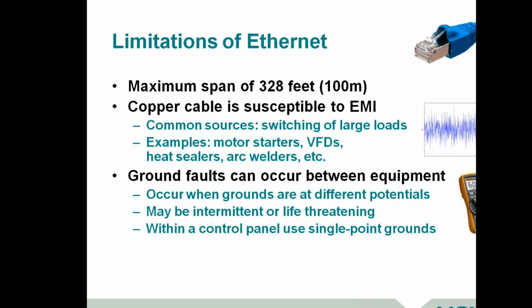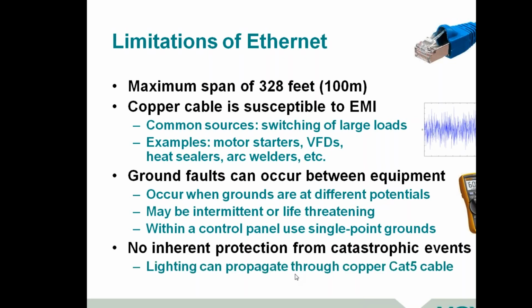Some of you who have been around a while have found that you need to be careful when plugging in test equipment or even a laptop. I know in a past life as an applications engineer, a common thing was if you weren't careful, you'd take out the ports on your laptop, and that's simply the current trying to find a quick path to ground. And lastly, there can be catastrophic events, like lightning, in a building or a remote application.